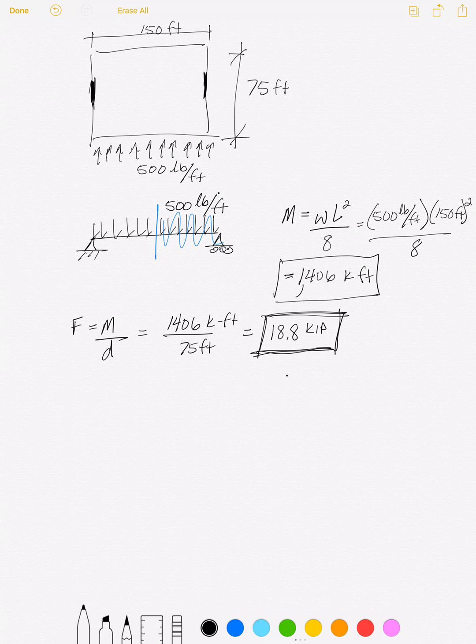Now, part 2, let's determine the required diaphragm shear. Sorry, we're not utilizing drag struts because I said not to utilize drag struts. And so we need to find out what is the diaphragm shear minimum capacity. We're looking for a capacity. So this is problem 4.